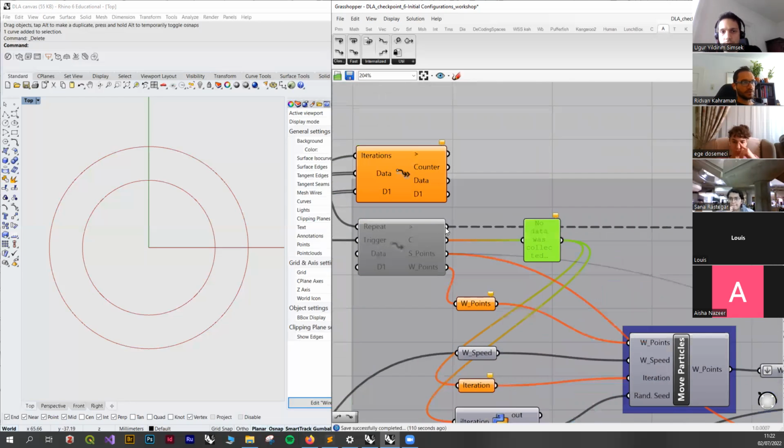And then I'm going to drag again all of these inputs and outputs back into this component. I'm going to disable it first, just to make sure it doesn't run. By the way, the way I'm disabling is I'm right clicking and pressing this, right? Or you can right click on the canvas and there's disable. But if you just use the keyboard and press D, it will disable it fast, right?